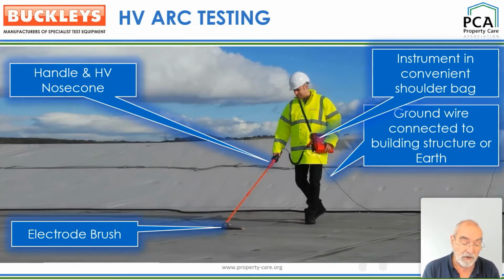The necessary test voltage is dependent on the thickness of the layer to be tested, with an additional allowance. Various published standards exist that provide this information. The better instruments also provide automatic voltage calculation according to the various published standards, allowing you to directly input the thickness of the material to be tested. The instrument will calculate the voltage.